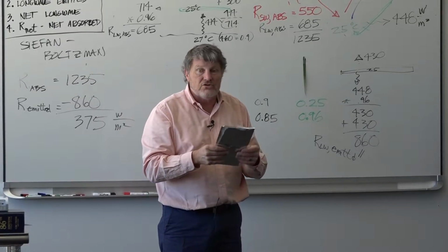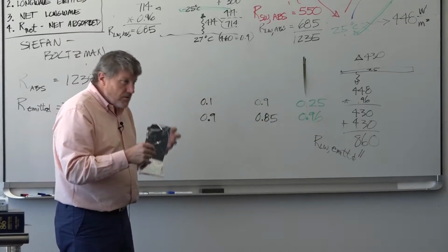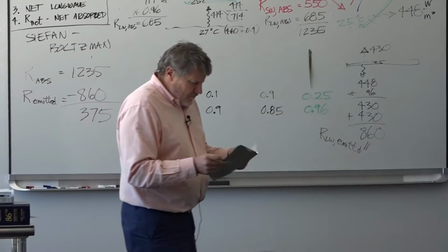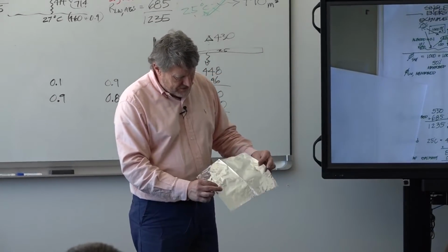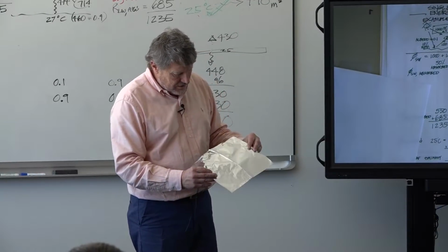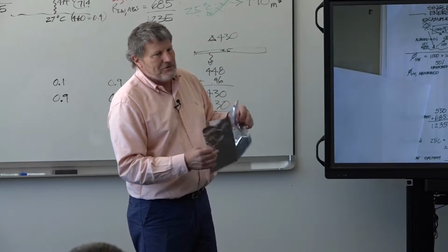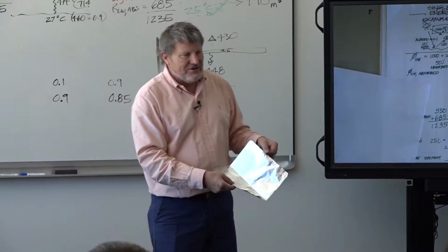It's nothing to do with conduction and convection. It's all radiation physics, keeping the warm temperature in. People say, my grandmother always says, put the dull side out on potatoes in the oven. You can read on, people argue about that stuff online. It turns out it just doesn't matter. The dull side is really close to the outside, and they're both low emissivity sides.